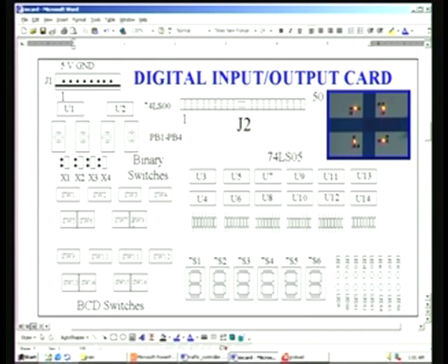And each time you want to set for main traffic delay, you can use 2 more jumpers here. In the SW1 switch, the last 2 bits you allocate for selecting which of the 3 timers you are going to select.